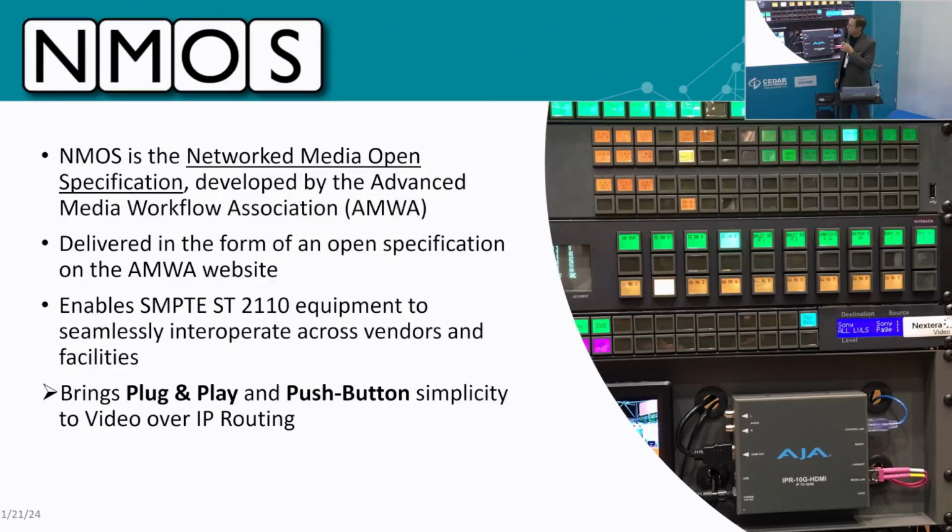I've touched on NMOS before. Let me describe how NMOS works, because this really is a key component of this. So NMOS stands for Network Media Open Specification. It was developed by a group called AMWA, Advanced Media Workflow Association. It's an open specification that's published on the website, and its goal in life is to enable 2110 and IPMX equipment to operate seamlessly, much like we did with HDMI cross-point switches and SDI cross-point switches.